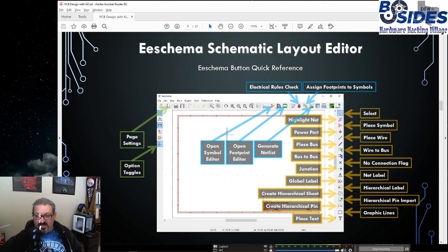So it starts with the simple select. You can highlight a net, and that would highlight all the things connected between 2 points, all the wires. We can place symbols. We can put in power ports. We can place wires or buses. We can move from a wire to a bus, or from a bus to a bus. We can put a no connection flag in here. And that's important when you're doing electrical checks. If you have a pin on some device that's just not connected and you don't use a no connection flag, it's going to throw a warning that you have an open there.